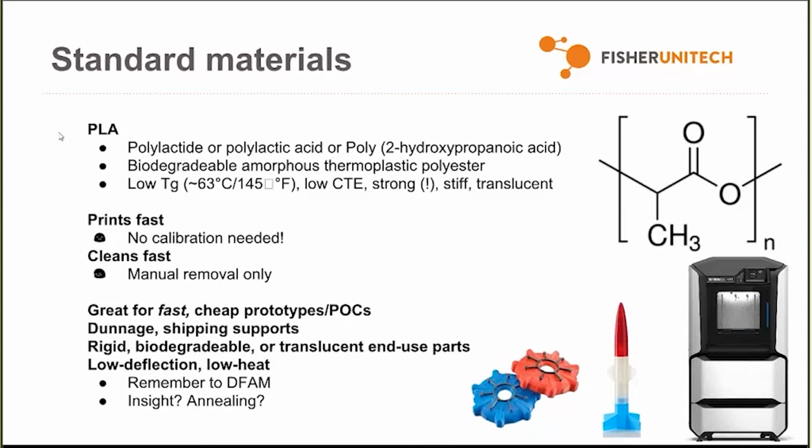Now, if you have an F123 series printer, like an F370, for example, you should definitely be using PLA for quick and dirty proofs of concept, like, for example, validating hole placements. Imagine a very large plate where the most important element is the hold-down hole pattern. Maybe just build that much, cancel the build, yank it out, test it, and then print the finished part out of another material.